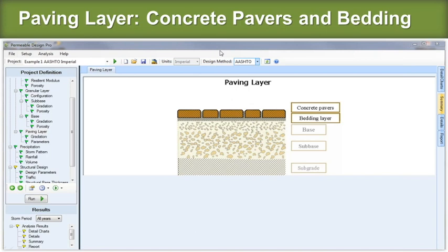These are not like conventional pavers, all right? Permeable pavers are purposely designed units that are spaced apart a little wider than normal pavers would be, and you do not put sand in there. If you ever see a permeable pavement that says put this bedding sand down or this joint sand down, it's wrong. You can't do that. You're not going to get water into the system.